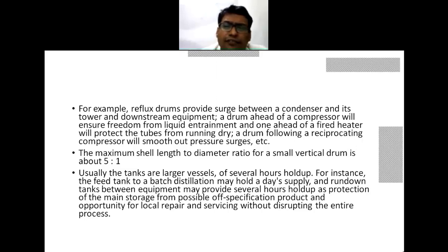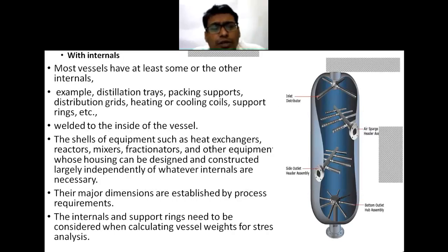So the main thing is that for the tanks the hold up is more, and for the drums the hold up is a few minutes or a few seconds. Now the vessels with certain internals, and these are the most common vessels. With the internals, in a reactor you will have an agitator and an impeller.